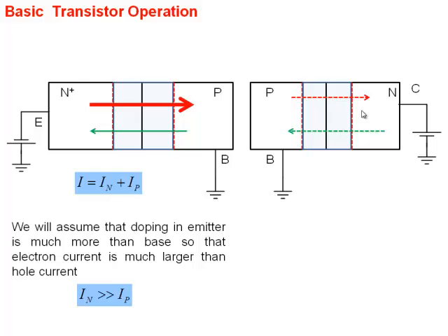Also realize why is the current so low? It is because the number of electrons here is very low. Electrons can easily flow into the N side. That's not a problem. But the number of electrons is very low, and similarly, the number of holes is very low. So that's the reason why current across this junction is very small. Now, if by some means I could increase the number of electrons here, then obviously the current can be pretty high. So it's low only because the number of electrons in this region is low.